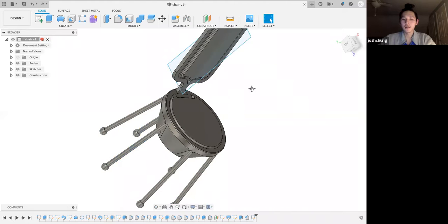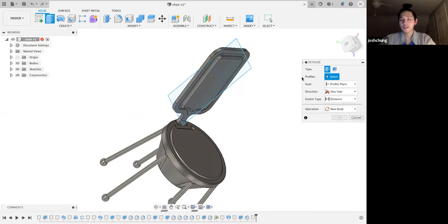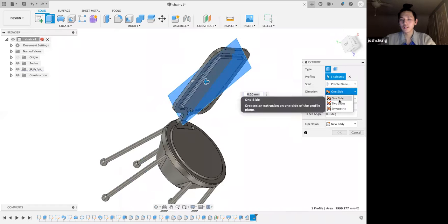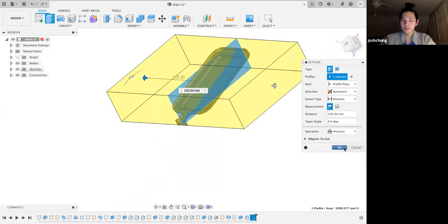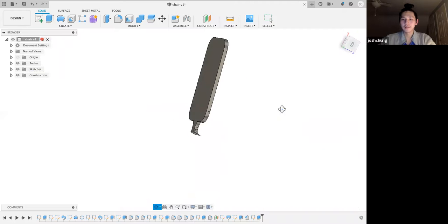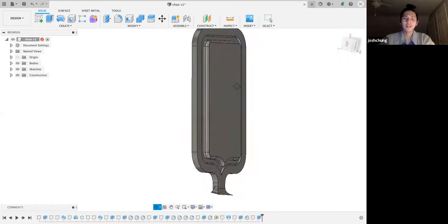And then later on, add this back, then extrude this. Do symmetric now. Do intersection and 3D print this part. So this is probably the most common way you're going to divide your large pieces into different sizes, so you can actually print them.